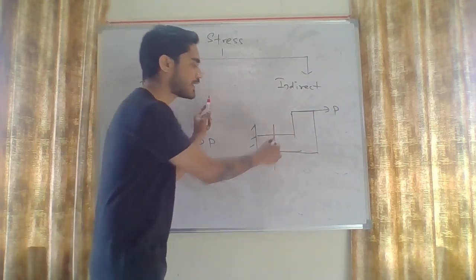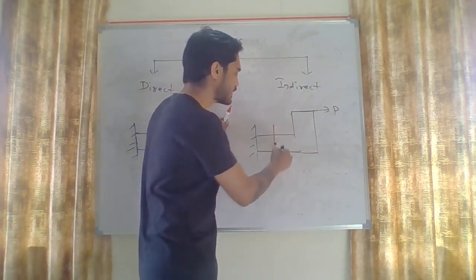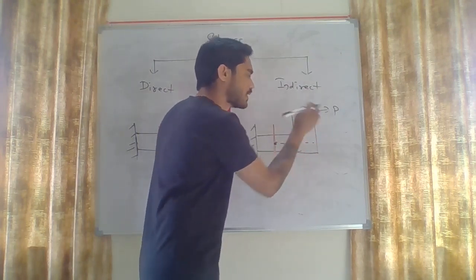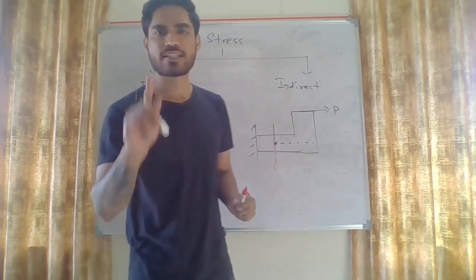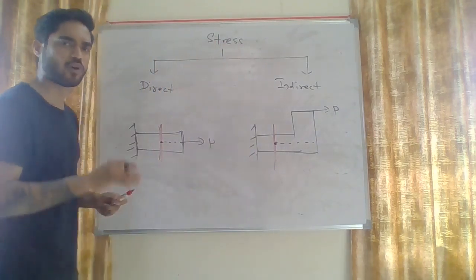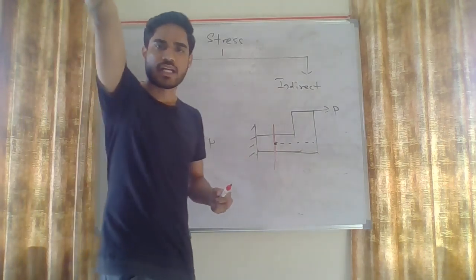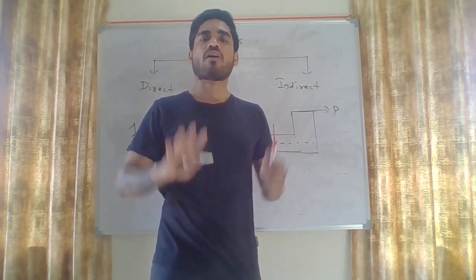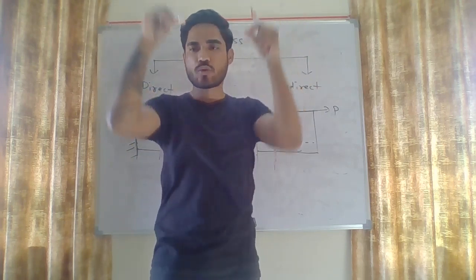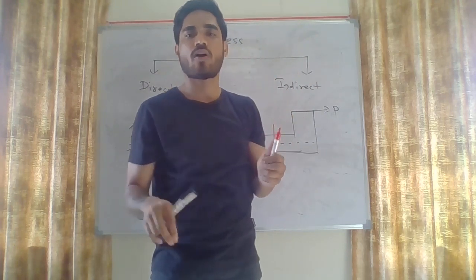Okay. So in this case, what do you do? In this case, you will transfer this force P on the centroid of the plane. My friends, note this down. Whenever a force is acting somewhere else on the body and you want to calculate stress on a plane, all the forces have to be transferred to the centroid of the plane.